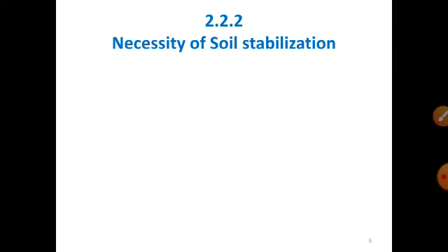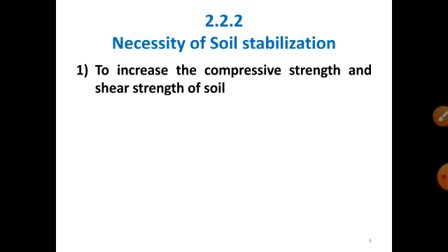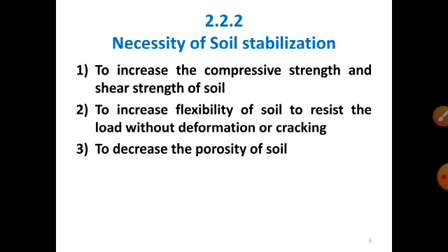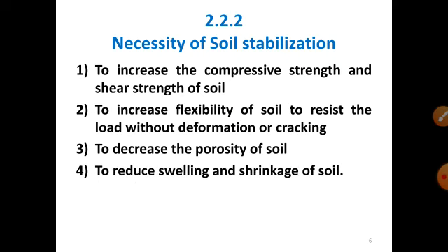Second, necessity of soil stabilization. First necessity is to increase the compressive strength and shear strength of soil. Second necessity is to increase flexibility of soil to resist the load without deformation or without cracking. Third necessity of soil stabilization is to decrease the porosity of soil. Fourth necessity is to reduce swelling and shrinkage of soil.